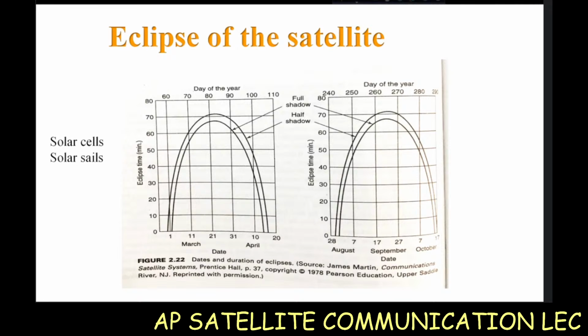as we approach the day of the equinox. Why equinox? Because that is the period of time when this kind of geometrical configuration is satisfied. That is, you have the sun, earth, and the satellite all lying in the same plane and along the same line. So under this kind of situation, that is when the equinoxes happen, once during March and the other around September. This being a natural phenomenon, we cannot eliminate this effect.